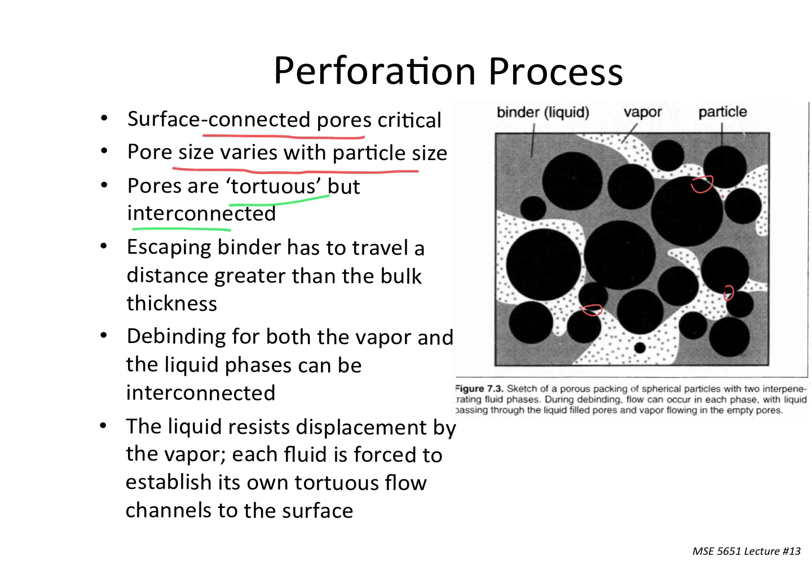And so because that's all going on, there's a lot of porosity, and it's interconnected. The binder has to travel a distance significantly greater than the bulk thickness. This is typically, here we're talking about thermal degradation, in that we make gas, but the gas doesn't have a straight line to the surface. It meanders around and goes here and there and everywhere, so it can travel quite a bit before it actually leaves the compact. All right, so it's driven by pressure and concentration, but it doesn't make a beeline to the surface. It follows this tortuosity around for some distance.